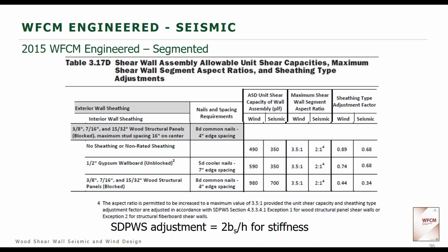We take into account where it says in the wind and seismic provision 4.3.3.3.2, where you take the larger of the one capacity or the lesser of, and then multiply it times 2. So we use that as a guideline to come up with these factors that are shown here. It's just not something pulled out of the hat. It's based on the wind and seismic provisions.